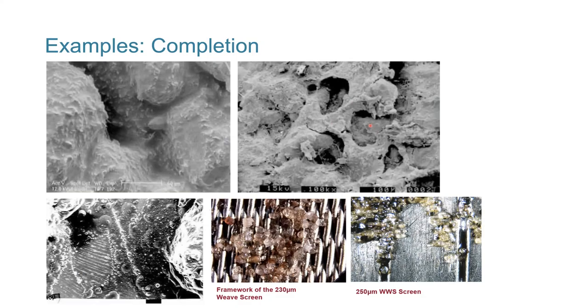Lastly, we have this one, which I like, because this one shows one of the reasons why lab simulations are useful, because in this reservoir, it was an open hole gravel pack, and we had a drilling mud that when tested alone performed really well. And the screen, when tested with the sand, performed really well.